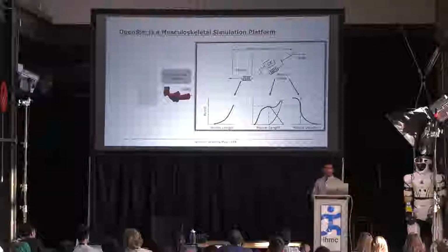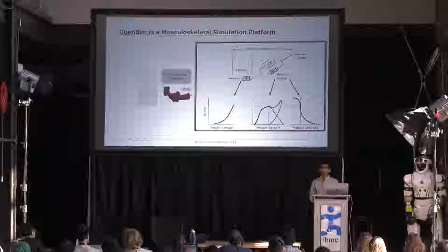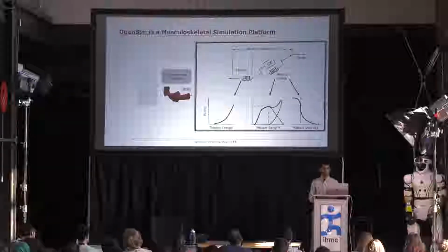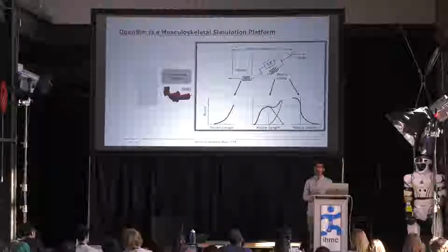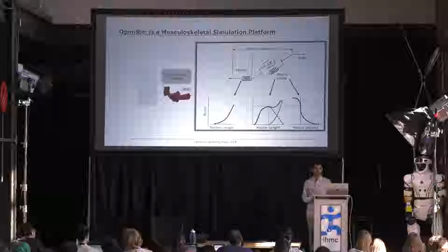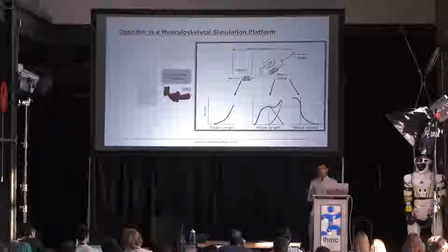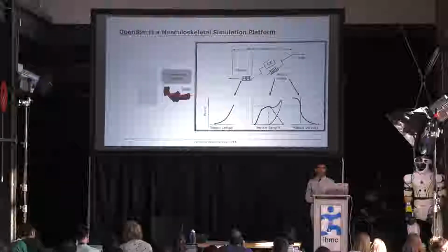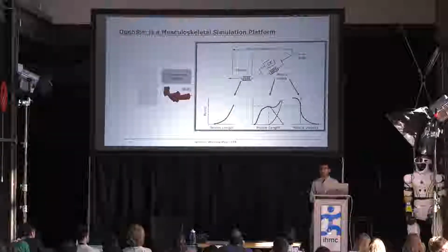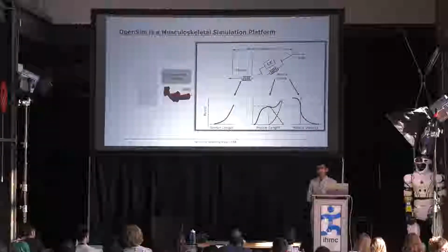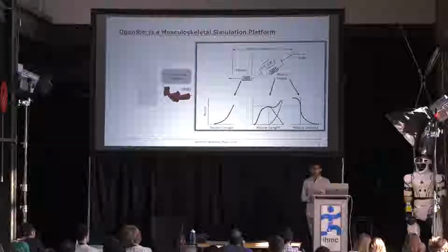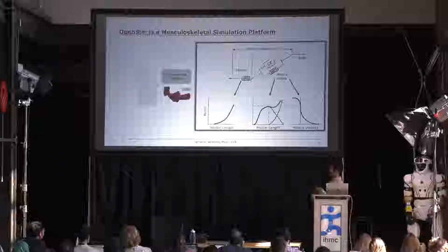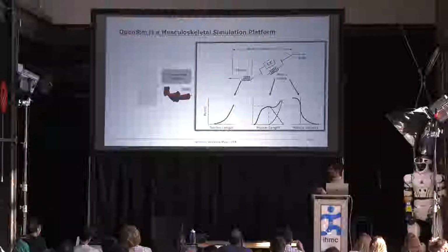So the muscles. Most OpenSim muscle models are Hill-type models. These models capture the delay between neural excitation and when our muscles actually generate force. That's what we call activation dynamics. The muscles in our bodies attach to our bones via tendons that have some compliance and can store energy, and we model those tendons. Those tendons are described by this force-length relationship for the tendons here.